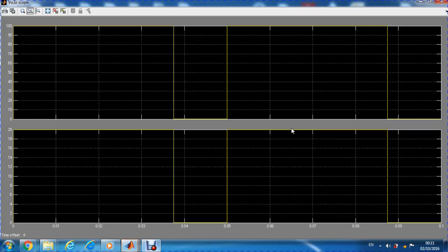If you look at the waveforms, the maximum is not changing, because only the average value changes. The width of the pulse has changed, of course, because we have increased the pulse width of the pulse generator to 75%. That's shown here.